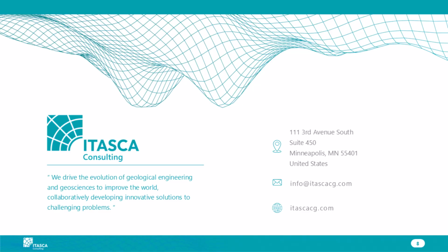Related to this topic, let me elaborate a little bit more, because in several projects, we have a 3D distribution of, let's say, borehole CPTs and stuff like that. So we are using a slightly different approach in that case. With the help of Ryan, who is our guru in terms of this Rhino geometry subsurface model, we create a database inside Rhino in which we have all the properties, the location of the property, whatever the interpretation is. And then we build a mesh around that domain in which we have all the properties distributed in the Rhino model. And then we use some kind of interpolation schemes to try to interpret, for what is possible, some sort of spatial variability, depending on the zone size and the distance and different interpolation schemes, so that we have a 3D distribution of the property of interest.